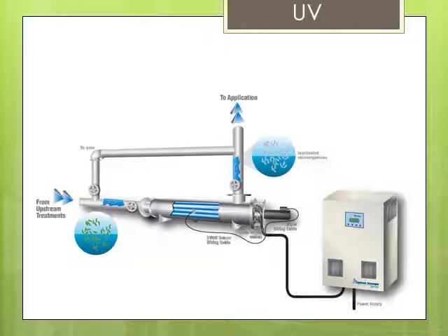Another one, and this is one that concerns me with greenhouses, is that these quartz glass tubes, they have to be quartz because normal glass absorbs UV. We want the UV to penetrate through the quartz into the water, so we have to use quartz. But anyways, the water that's coming back leaves residue on the quartz. Say this is my quartz tube. Over time, you get a film of minerals and whatnot that form around the quartz, and the UV, which used to be really strong, ends up becoming kind of weak because a lot of it can't penetrate through that film.